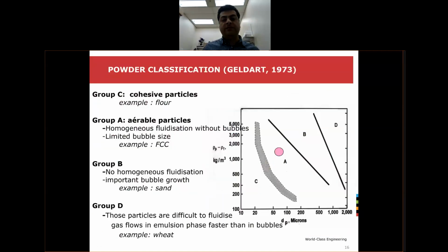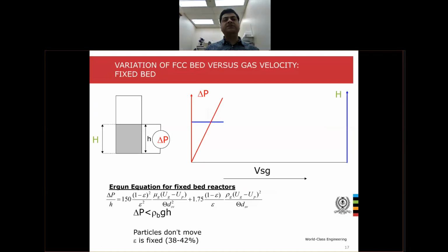practiced by fluidization engineers is always to control the height of the bed versus pressure drop. It is very important because if the height of the bed is too high, you may lose your material, and if it is too low, you don't have good reaction performance. So it's always important to have an idea of the bed height. And to measure the bed height, you usually use the pressure drop along the reactor.